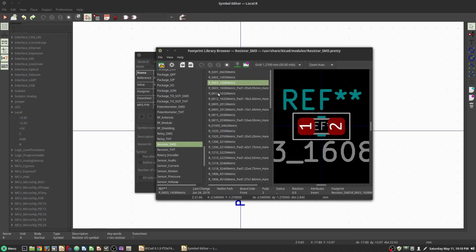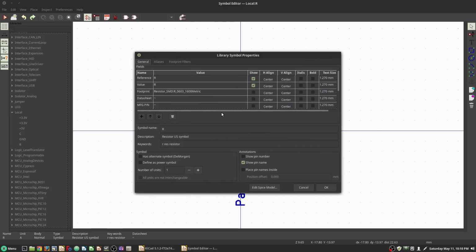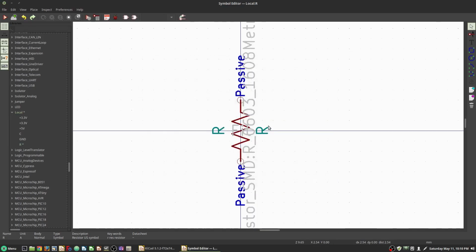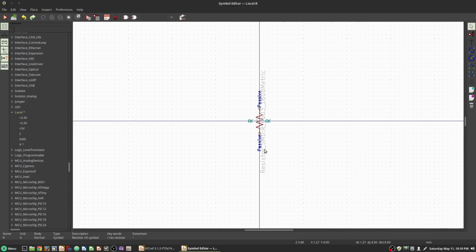I don't have trouble soldering to them, so I just grab that one, since a lot of the work that I do, especially professionally, eventually will go to a pick and place machine with a solder stencil, so that really won't be that big of a deal. So I'm just going to go ahead and select this one. You can double click on it and that will fill that footprint, and we'll hit OK, and that will post a lot of these things into here.